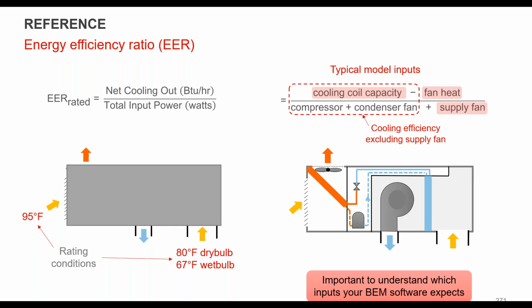Yeah, and so again, for EER, just following up on Craig's question of whether it's using gross or net, the rated EER value is net. That is just the rated condition. So it's already taking out the heat from the fan. So again, when you have to go back and translate it, that's the way that they do the test for them. So again, it just makes it more convoluted for us.